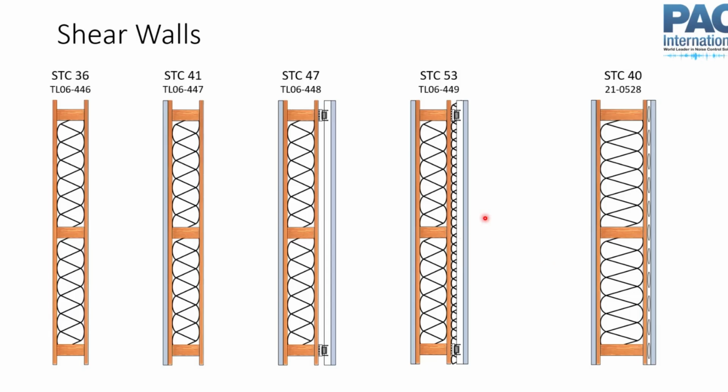If you only have shear panels on one side, if you can put the shear panel on the side opposite your resilient channel, clips, whatever your acoustic isolation is, then that can work really well and you don't have to worry about this as much and you'll get better performance out of your wall. But sometimes that's hard to do, even if you have only a single shear panel.